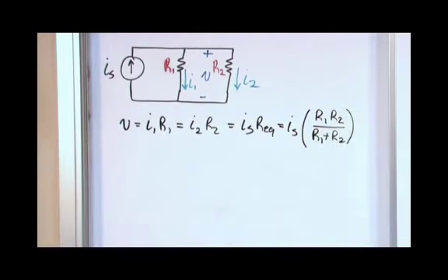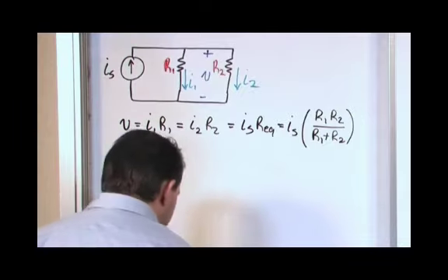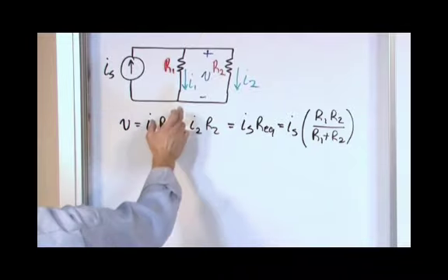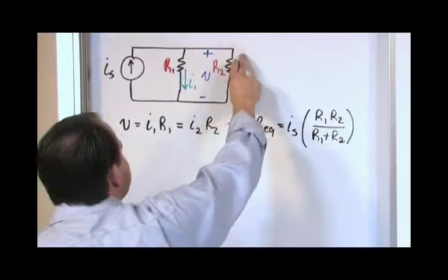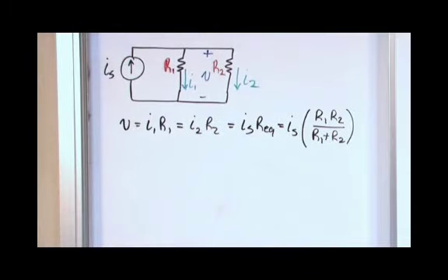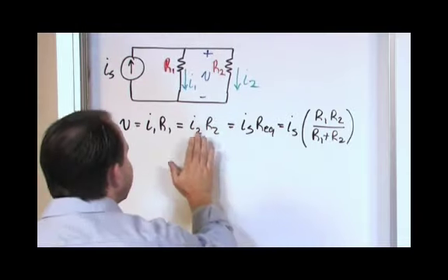So what we've really drawn here is a very massive thing, but really what it says is that the voltage across this is the same as the voltage across here, the same as the voltage across here, and the same as the voltage across an equivalent resistance, which I know how to make. That's all this is saying. Everything is equal to each other.